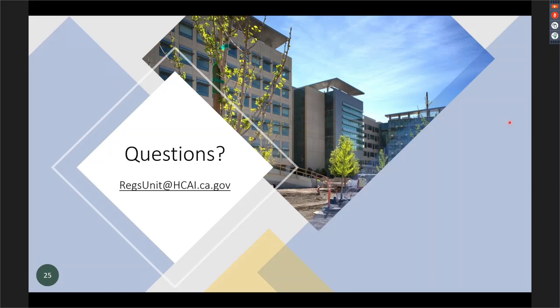So Richard, as it pertains to the stamps on the NMAs, the question reads, whose stamp goes on the NMA form? Only the DPOR in responsible charge or the individual discipline engineer stamp? And does a stamp need a signature? Thought we already answered that one, but the drawings have the same requirements of any ACD. Whoever made the changes, stamp and sign the drawings.